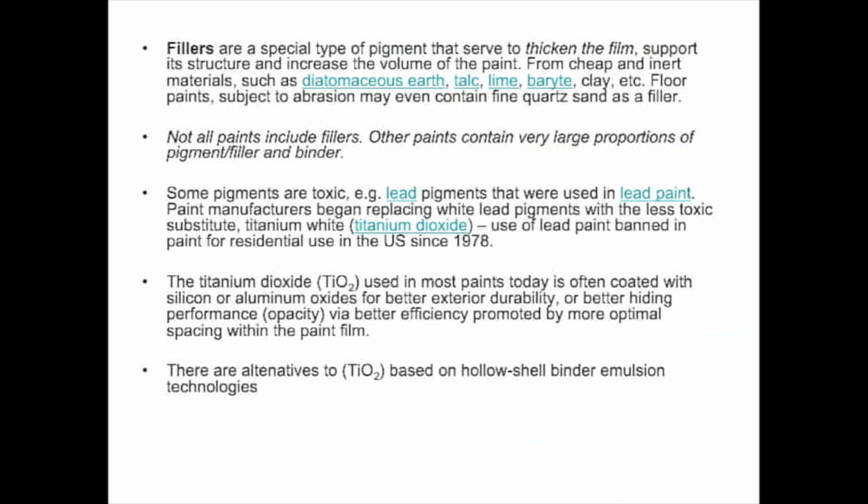Other terms, so filler. Filler is usually used to control the viscosity or thicken the film, and this has to be as economical as possible. This could be based on talc, diatomaceous earth, calcium carbonate, and so on. Okay. Then we discussed titanium dioxide, so I won't repeat those statements.